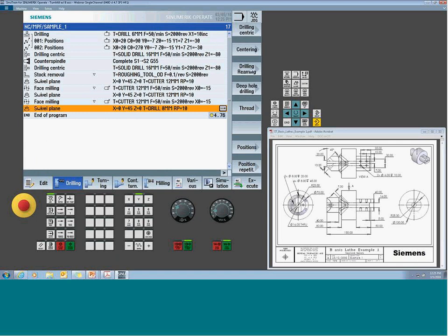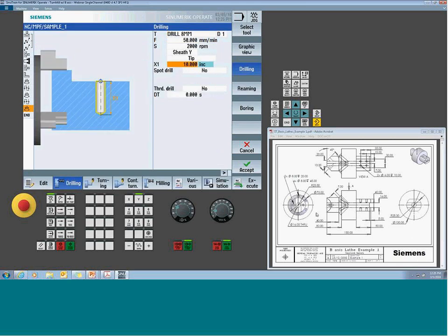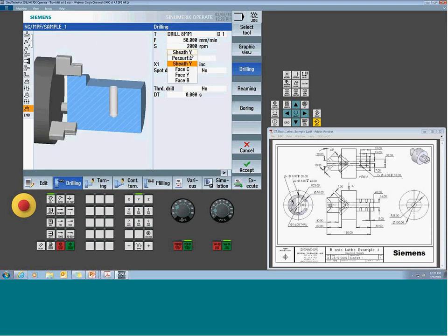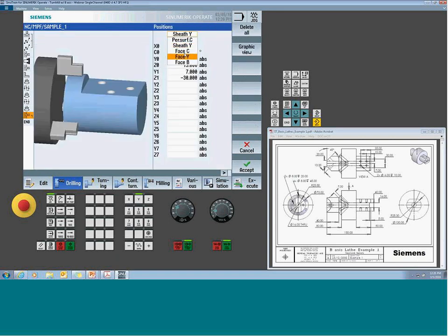From there, we're going to use our cycle. Do a basic cycle, 8mm. I know my depth is in my call out, which it looks like is 2mm deep here. And make sure this is B. That's important, right? And then I go to my position locations. I can do some random locations.